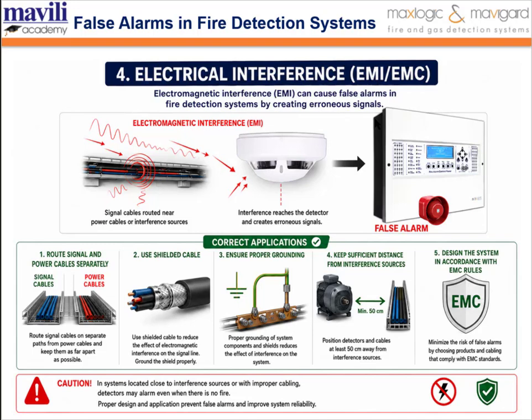Therefore, cabling in accordance with the EMC regulations, using shielded cables, filtered equipment, and applying proper grounding, proper earthing, and routing signal lines at a sufficient distance from powerful power lines will importantly reduce the risk of false alarms. This type of EMC regulation has extremely complicated structures, and the tests are also expensive.